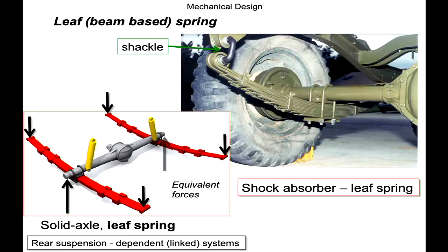Well, they've played around with the idea that if there's no load, not much mass being carried, then you can have a gentler ride. You don't need as much spring. As load increases, then the overall spring will start to deflect. The tray of the vehicle will start lowering to the ground, and more of the spring sections or beam sections come into play to help support the load.